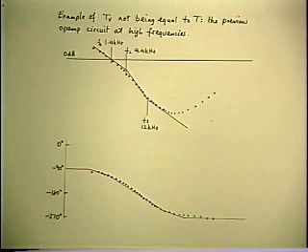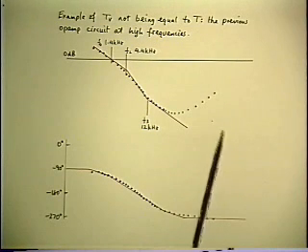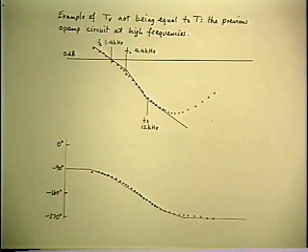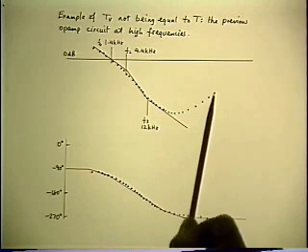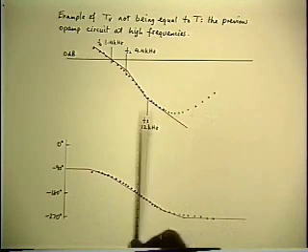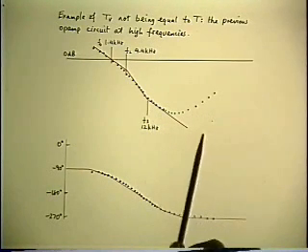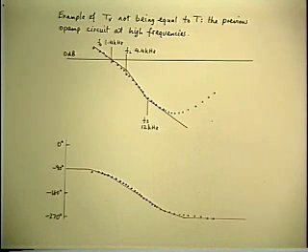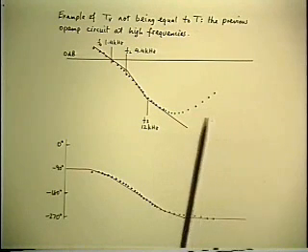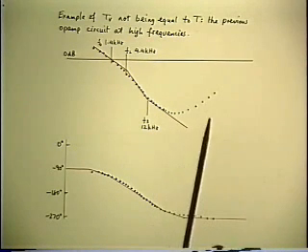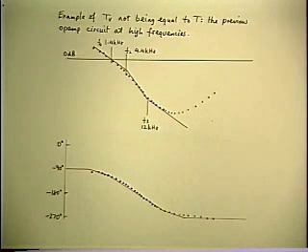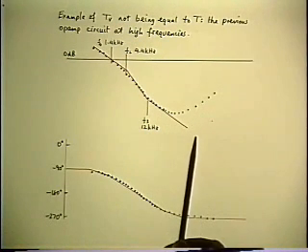And so we'd better check into the other possibility that we're not measuring what we think we're measuring. And the most likely reason for that is that the measurement we've made by injection of a voltage at a point in the loop, it's turning out maybe that it isn't an ideal point. And maybe we're not satisfying those impedance inequalities, which means we are not really measuring the true loop gain, we're measuring something else. So that's the thing we need to go back and check up.